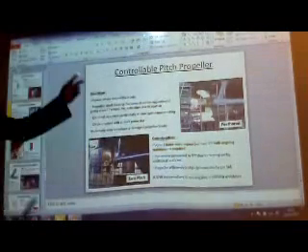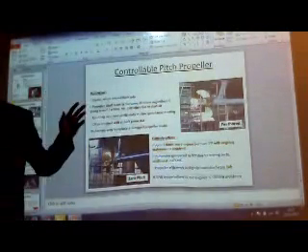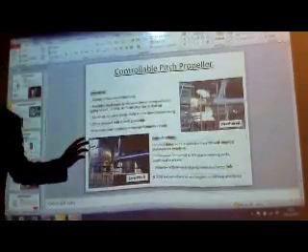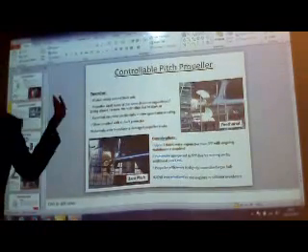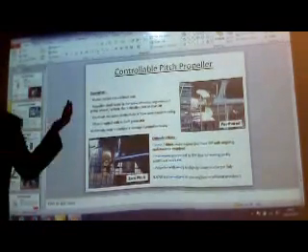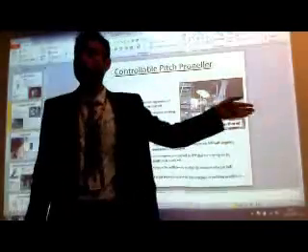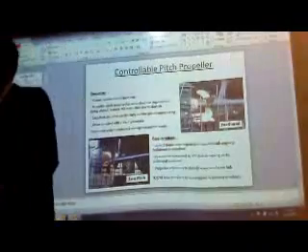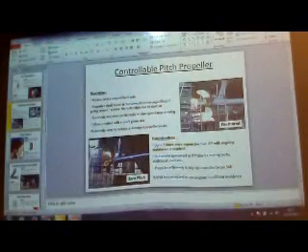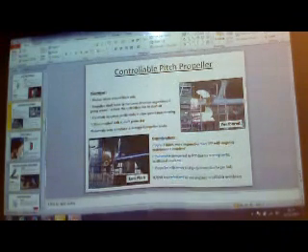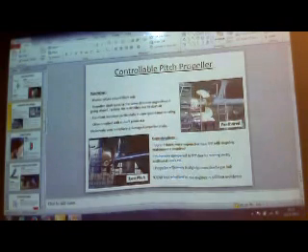So what is going to happen here? The RPM is going to be steady in this case. Generally, you can change it if you want, but generally the RPM will be kept steady, and what they will play with is the pitch of the propeller. They will change the angle of the blade. If you change the angle of the blade, the pitch will increase and decrease, which can then relate to speed. So you don't have to go again and again and change the RPMs, leading to different fuel consumption, spikes in fuel levels, engine stress levels, and the constant need of one person manning the engine room.